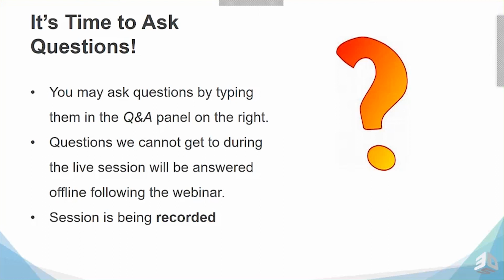I'm not specifically sure about that EOS machine. I know that at a minimum, not just EOS specific, you can export CLI and slice files and put them into whatever your particular brand machine's hatching software is to actually draw the weld paths. But I'm pretty sure that there are some machines in the library that you can export directly to. But that might be one that you might want to contact us directly about for your specific machine.